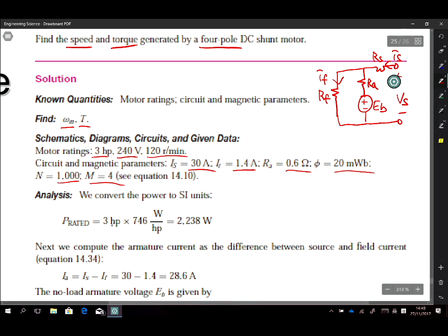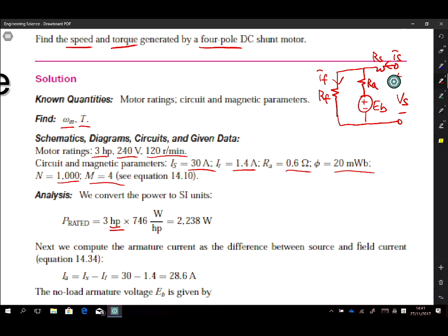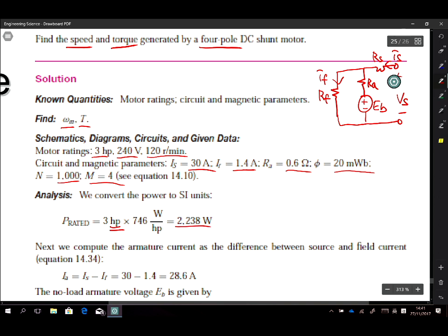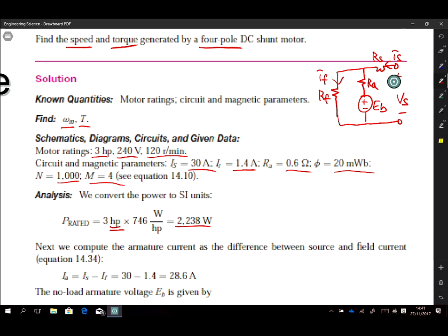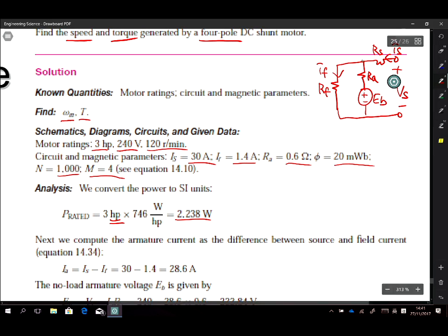Do you know what HP is? You are playing games, right, so you may think health points. But it is horsepower, 3匹. 3 HP means 3匹, and 1 HP means 746 watts. Therefore, we multiply the power by 3. You get 2238 watts.